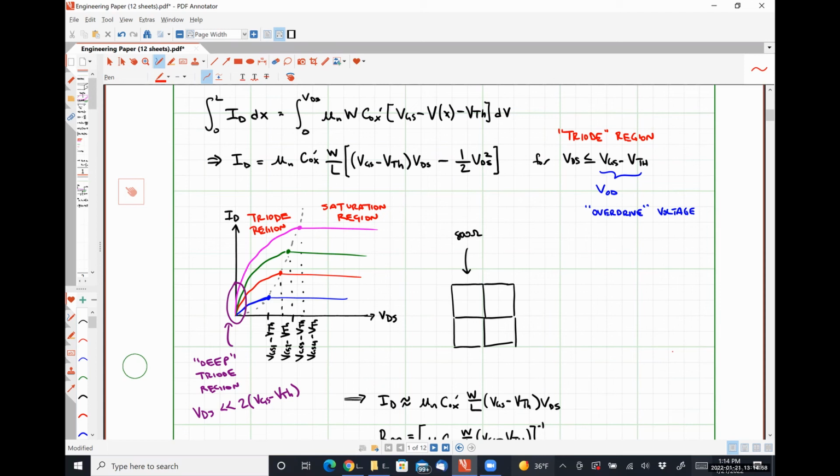And then this region here, our triode region, where our current is a function of VDS, is analogous to the region in BJT operation where our current is actually dependent on our base-collector voltage, or our collector-emitter, same effective thing. So triode is the same as saturation in BJT. So we have two different saturation region operations, which mean vastly different things for the two different devices.